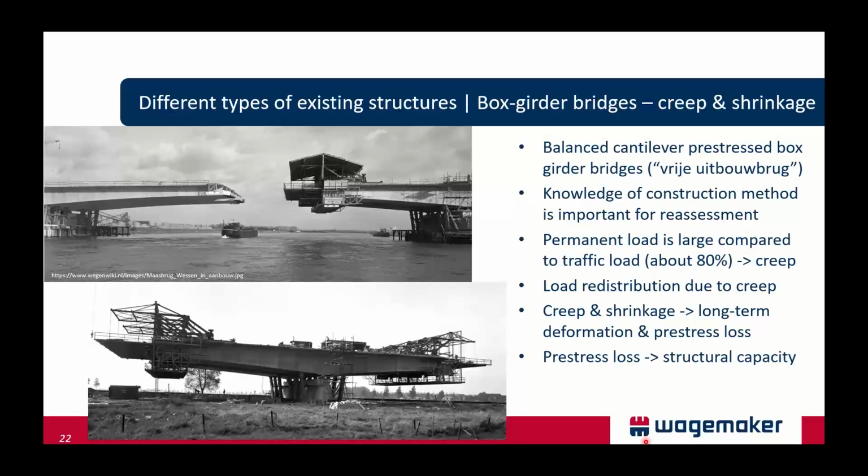Another important factor is that the permanent load is very large in these bridges, about 80% of the total load, and that is also why we put a special focus on creep, because of the high contribution of the permanent loads.